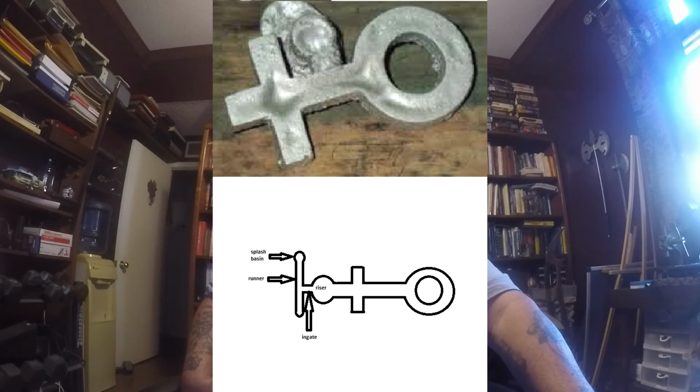When you pull that pattern, it would have gone straight down that channel all the way to the circular portion of that mold cavity, filled that up, and the very last thing that would have been filled up would have been the riser. That would have been a perfect way to feed and support the solidification of that casting, the directional solidification of that casting.